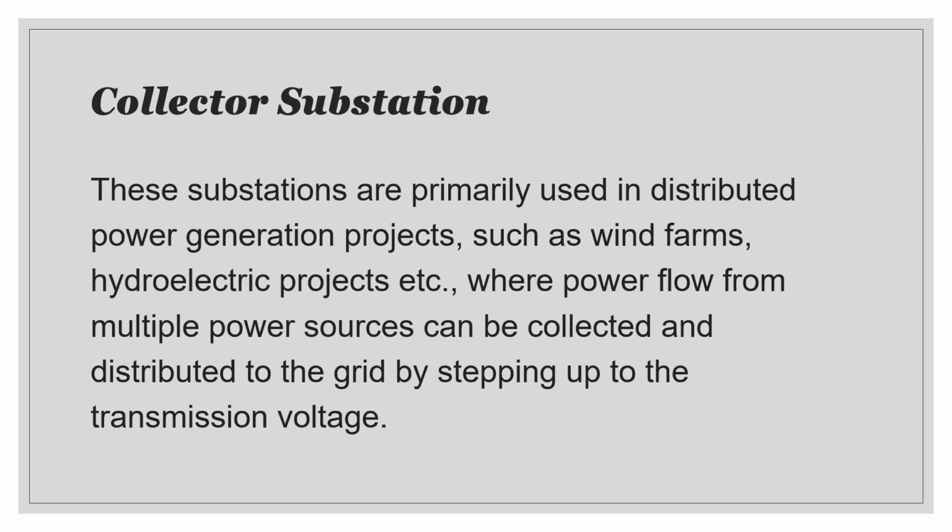Distributed, or you may hear the term embedded generation. So they are now embedded into the system, which was looking from generation out. It was generating facilities sending power out to consumers, so it was one-way traffic in terms of the electrical energy. With distributed energy or distributed generation, we now have power coming into the network from customers and from these other distributed generation facilities.